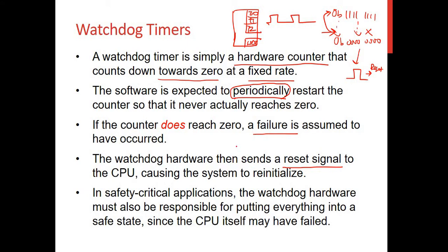Of course, in some safety critical applications, you must also ensure that you put everything into a safe state before you reboot the whole system. Because your hardware or your application, your device may be doing something that is critical, that involves safety or some very dangerous operation, and you want to make sure that you put everything into a safe state before you issue a reset.